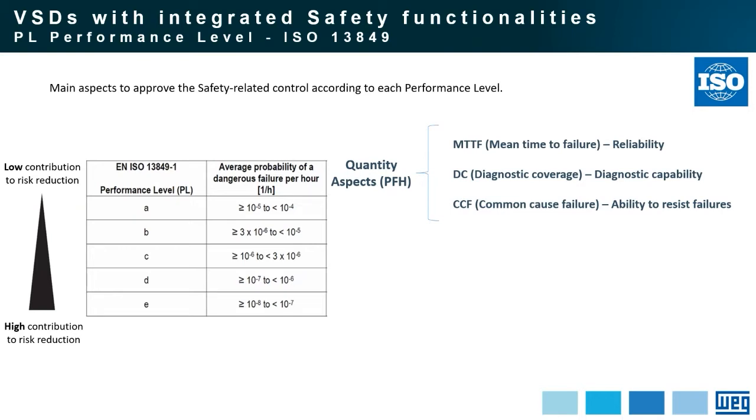And the mean time to failure, the MTTF, will evaluate in the end how reliable each component installed in the machine is. Additionally, there are the statistics concerning diagnostic coverage, or diagnostic capability: how the components will monitor and find internal failures. Another one is the common cause failure statistics, that in the end will check the ability to resist failure.